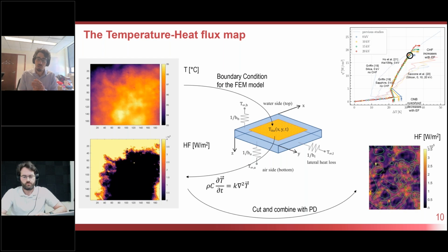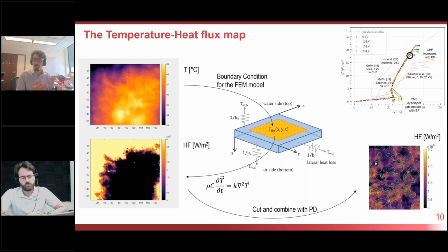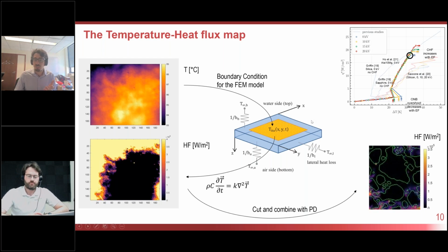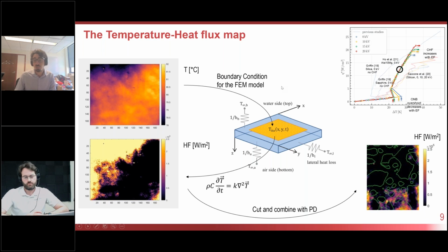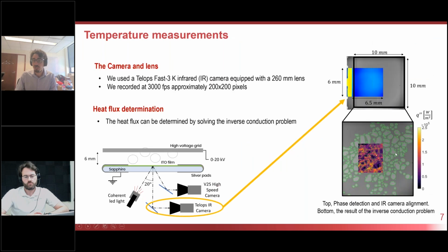And in this case, we're looking at a very low temperature variation on the surface. About the speed, the bubbles are, let's say, we're talking about centimeters per second. It's very normal for any boiling process, nothing particularly weird. But the difference maybe between this and water is that bubbles tend to be much smaller. So having much smaller bubbles means that you have like a bazillion bubbles on the surface, right? And so your IR resolution needs to be very high.